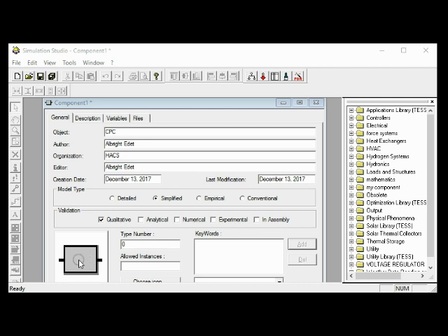And the user also has the privilege to modify the picture or replace it with another picture in Simulation Studio. Just any picture cannot be used in Trnsys except one with a .bmp extension, meaning bitmap. So if such a bitmap is not present in the Trnsys directory, the user can try to find this bitmap. Let's try to fix an icon for my CPC model here.